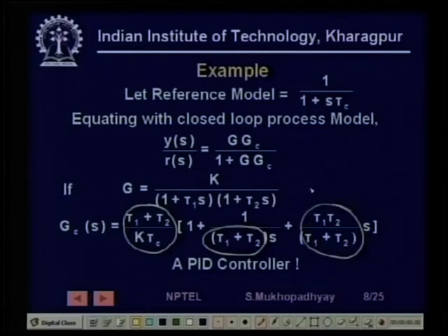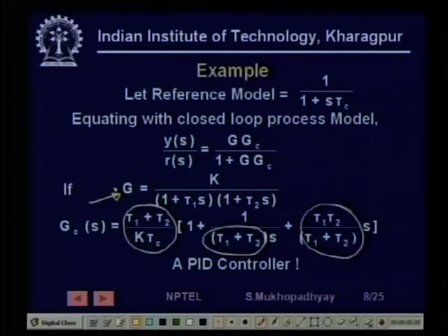And very interestingly, we never said that we actually want a PID controller. We just wanted this plant to behave like this model. Now, it turns out that for having that, the controller that you need is actually a PID controller. So it's very good. You see, PID controllers can give you good response.